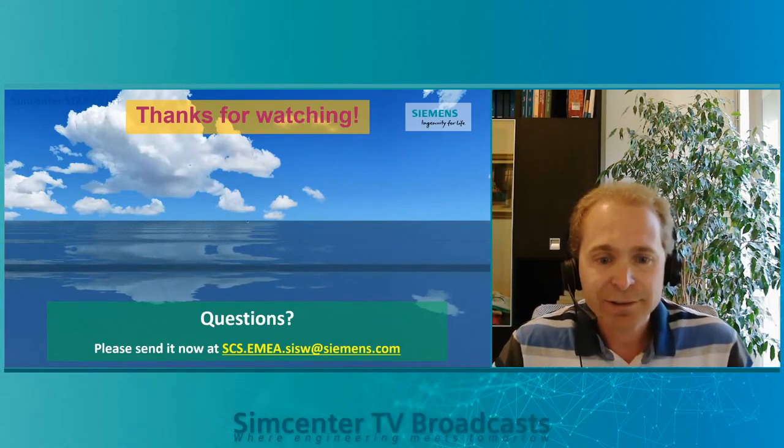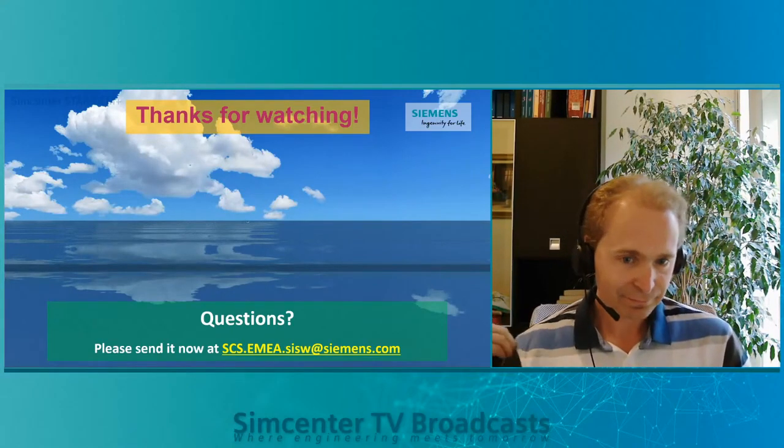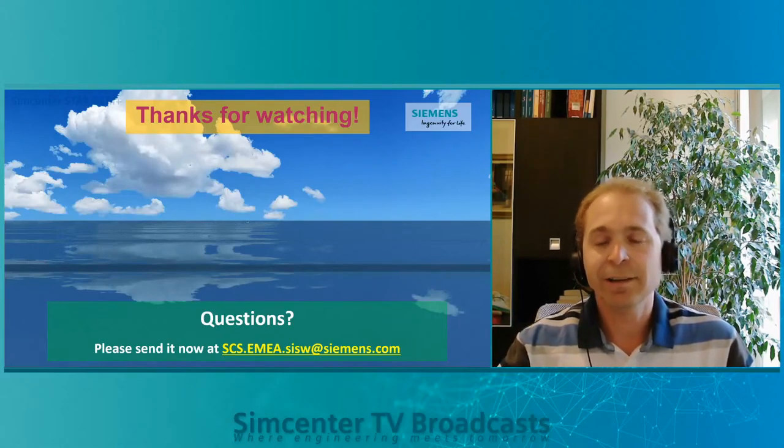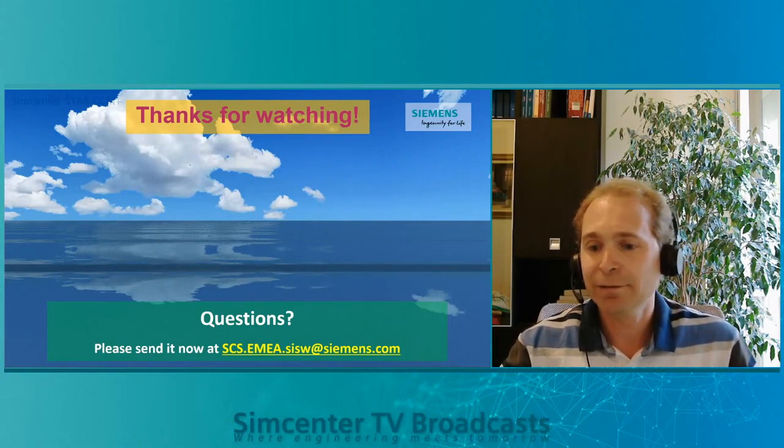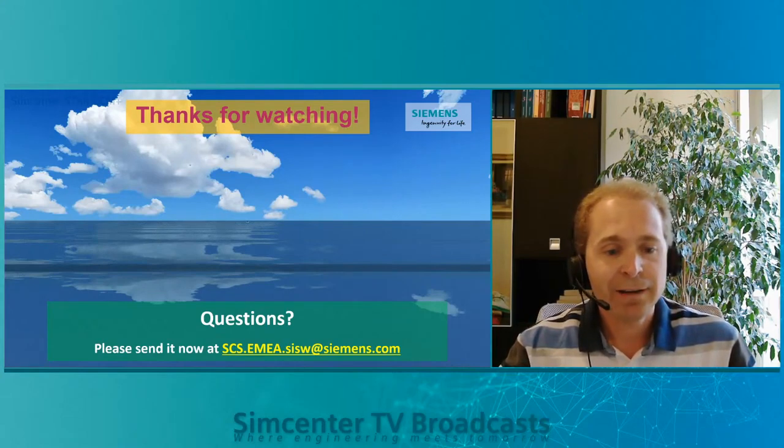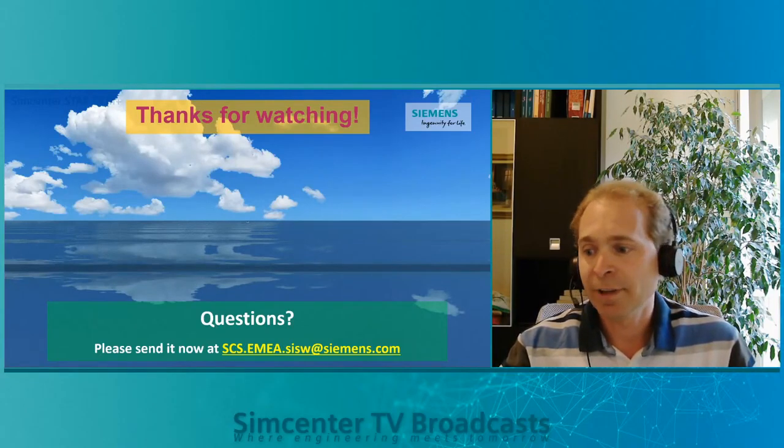Okay, how to insert wind associated with the waves? Well, wind is something that we can apply in the same definition where we define the wave. Indeed, in the VOF wave model, you can apply also a current and a wind. So again, it's not related with motion, and it can be applied in the physical setup.